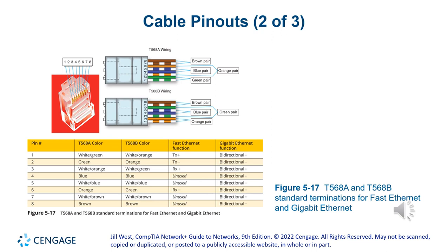And this is something that I always used to get confused about. If you look at this drawing, you see the little tab that is drawn on the two light blue connectors, right? That means that the tab is on the other side. You're not looking at the connector from the bottom, which is the side with the tab. If you flip it around to where there's no tab, then you can count the cables from 1 through 8.